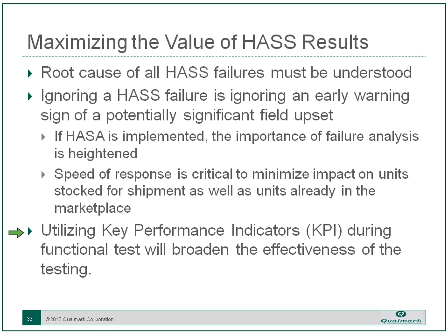In HALT, you can find out if those indicators are linked to hard failures and are valuable for determining if a product is marginal. If you found out that they are, utilizing those in HASS essentially widens your net. It makes all the testing more effective because you've found some new ways to catch what might be an issue on a product.